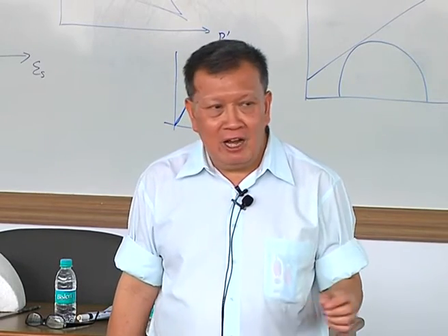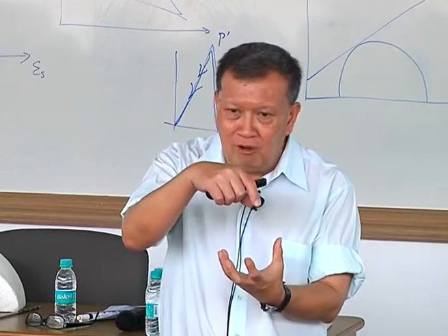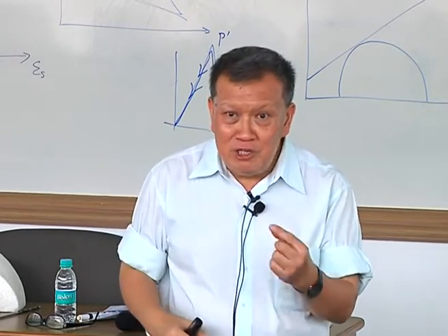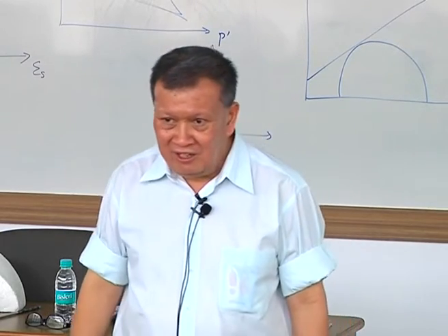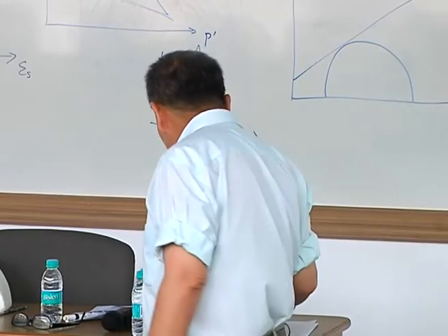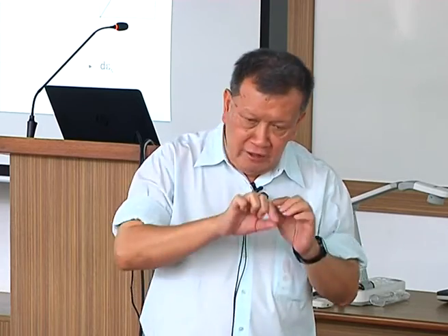In that sense, there's no such thing as a true undrained triaxial test. In the early days, they called it a constant volume test, because all you do is maintain the volume constant. But the shear band can still take in water if it wants to. Is that alright? So as a result, it's very hard to preserve. That's why a lot of people ask, can you truly preserve an undrained triaxial test? The answer is not easy. We tried it with cement-treated soil, again shear band.